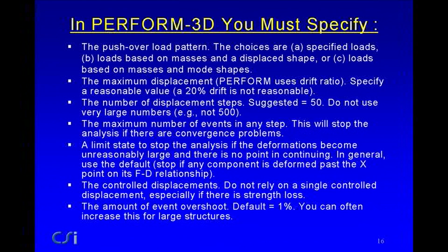The loads don't necessarily increase linearly. The load at any floor is the mass at that floor multiplied by the height up to that floor, which is really what you mean by a triangular load pattern rather than one which is truly triangular. So you must specify that. And the third choice is you can specify loads which are based on the masses and the mode shapes. It will calculate mode shapes, then construct lateral force patterns which are based on the masses and those mode shapes. So they're modal loads.